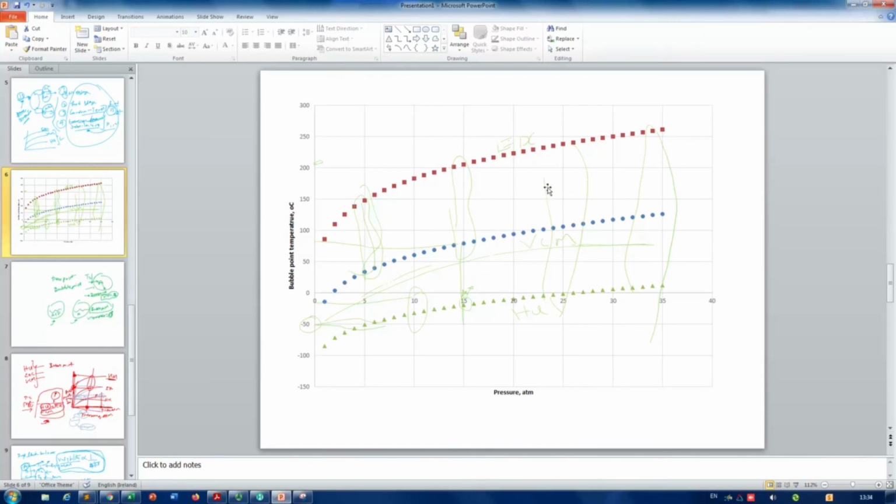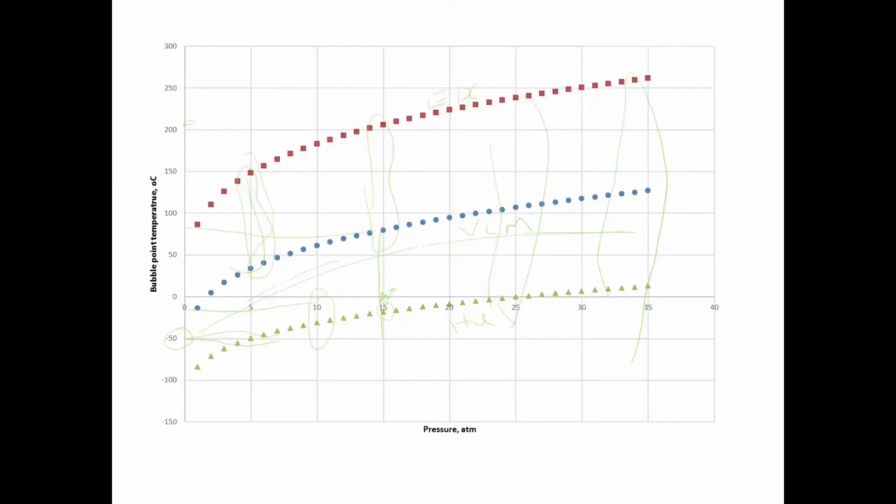So if you look at the graph here for a bit, you have 15 atmosphere. So let's maintain this pressure. So roughly around this temperature, your VCM should start to boil. So you can collect VCM in the top, and then in the bottom we can collect which material, ethylene dichloride.